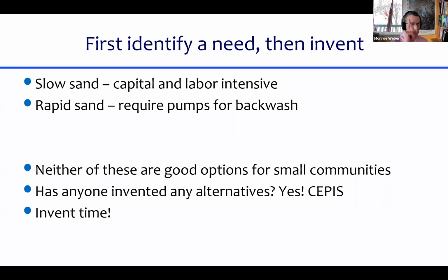Although granted, in London, where they have 80 hectares of slow sand filter beds, imagine the market value of that land, 80 hectares of land in London that is tied up in slow sand filters. And when they clean their slow sand filters, they have made very light, big tire motorized carts that can go out and scoop off the sand and carry it off the sand bed. But in general, you'd be doing it by shoveling. So we're not so keen on slow sand filters.